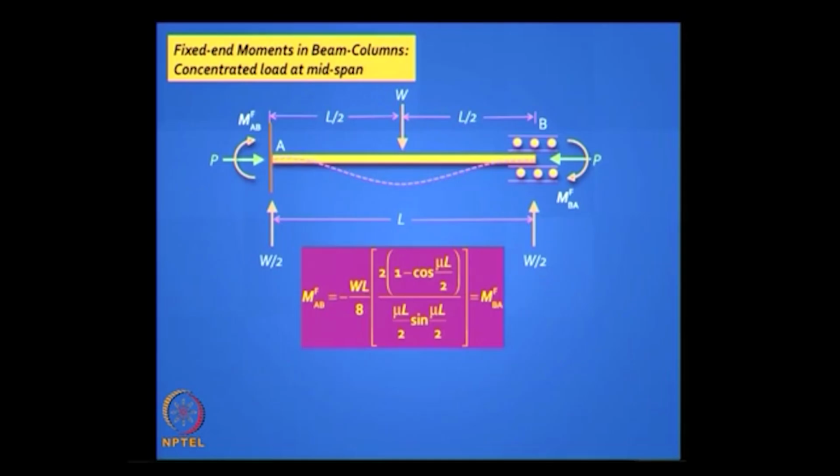Okay, now we need formulas for fixed end moments. For a prismatic beam, look at the boundary conditions shown. To apply a force P, actually you must facilitate it. So instead of showing fixity, you should show an ability for it to move horizontally, but you can assume it is actually rigid, but this is the correct symbol. Can you see it? This is the correct symbol instead of showing it fixed, but some books show it as fixed. It's really not very important.